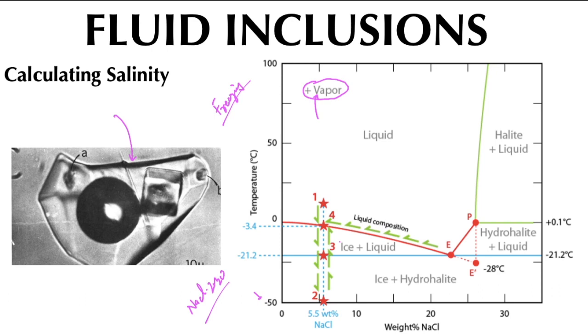Okay, so now you have decreased the temperature, it has solidified and reached this point 2 where it is at minus 48 degrees Celsius. Now what we do, we start heating it again. Now when you are heating it, it will reach till this temperature, which is the eutectic temperature, right? And then as you move to this point, this ice will start to melt, right? And NaCl will start dissolving in that ice. Now it will move along this line as the temperature increases. You are heating it and it will reach this point.